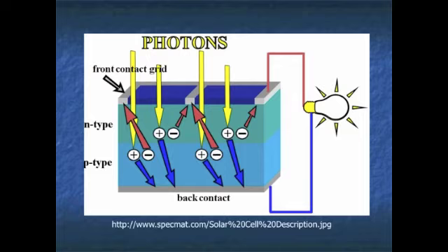Now suppose we shine light on our silicon solar cell. The sun's radiation carries energy, and some of that energy will be absorbed by valence electrons, popping the electrons out of their holes. So when photons of light hit the crystal, electron-hole pairs are formed. Due to the electric field at the junction, electrons are pulled up and holes are pulled down.